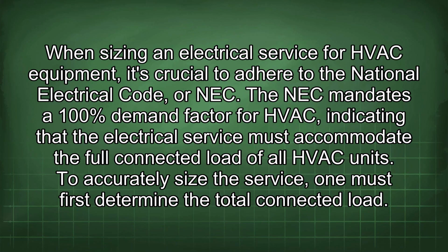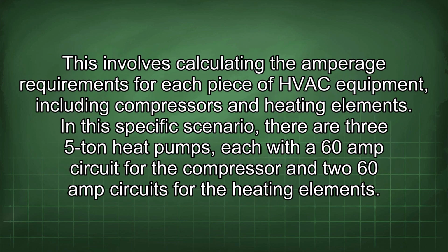When sizing an electrical service for HVAC equipment, it's crucial to adhere to the National Electrical Code, or NEC. The NEC mandates a 100% demand factor for HVAC, indicating that the electrical service must accommodate the full connected load of all HVAC units. To accurately size the service, one must first determine the total connected load. This involves calculating the amperage requirements for each piece of HVAC equipment, including compressors and heating elements.